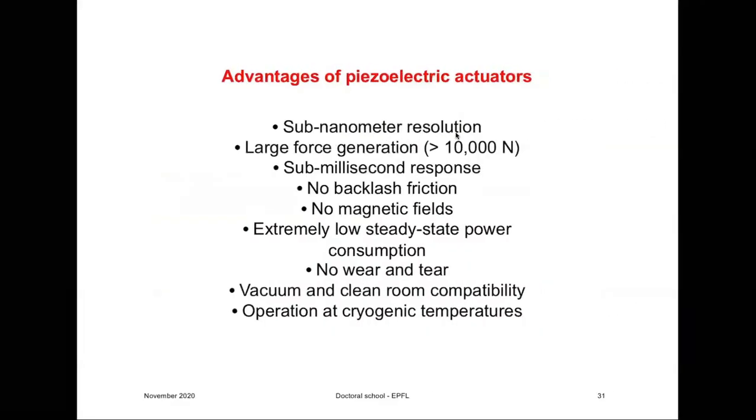So what are some of the advantages of piezoelectric actuators? Well, you have sub-nanometer resolution, which is very difficult to get with, let's say, hydraulic or electromagnetic step motors and other types. You can have generation of very large forces. You have a very quick sub-millisecond response. There is no backlash. There are no magnetic fields. This is very important, because sometimes in sensitive electronics, you cannot afford strong magnetic fields that you would have in electromagnetic actuators.